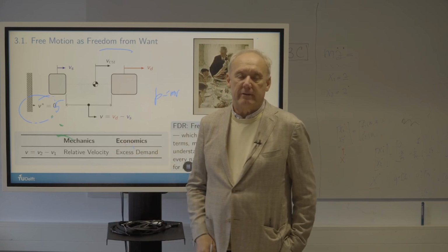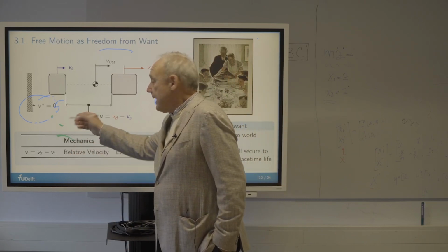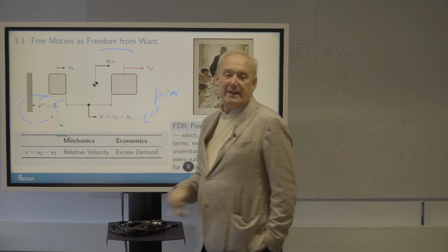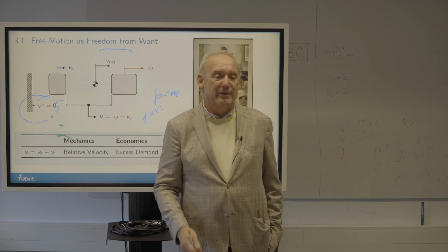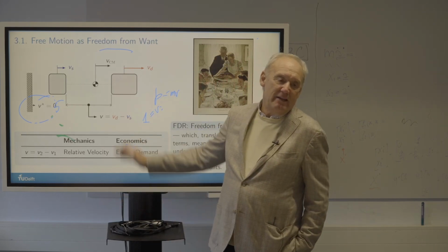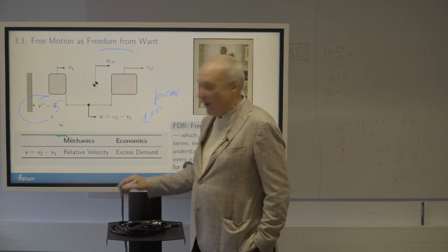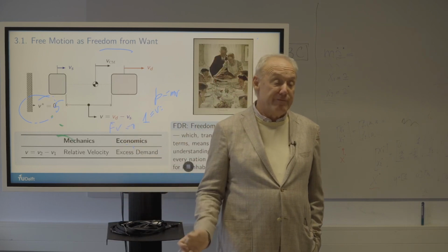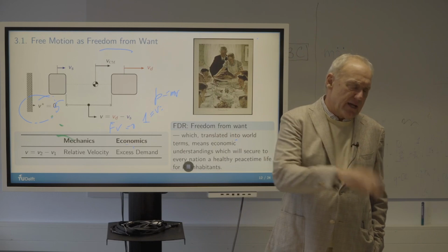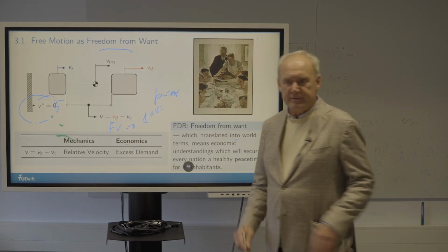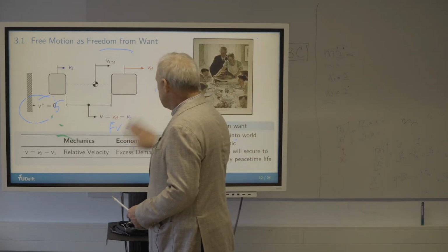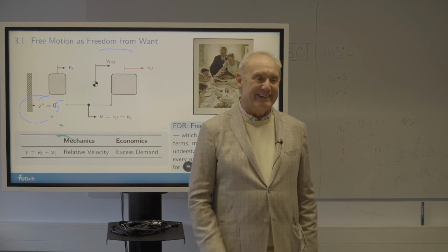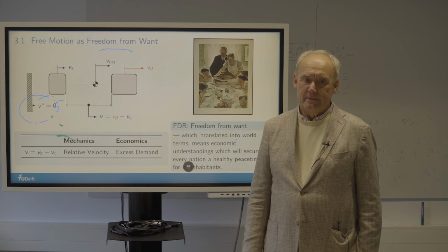You guys just did bond graphs, and you say, well, where is the I element or the one junction where there is a zero velocity? Well, it isn't there because there's no power flowing in it, so they leave it out. Because if the velocity is 0, then the force times the velocity is always going to be 0, so there will be no net power flowing in or out. So it's there, but left out, okay? I just overheard you guys talking about these bond graphs, so I don't know.